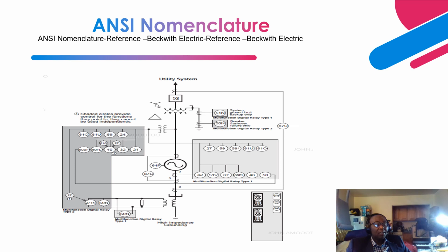Next is 27TN. This is a third harmonic undervoltage relay, and it complements 59N. Like I made mention, the 59N stator ground fault relay is made to see only 95% of the stator winding, right? So the remaining 5%, this relay does not see and does not cover that region.